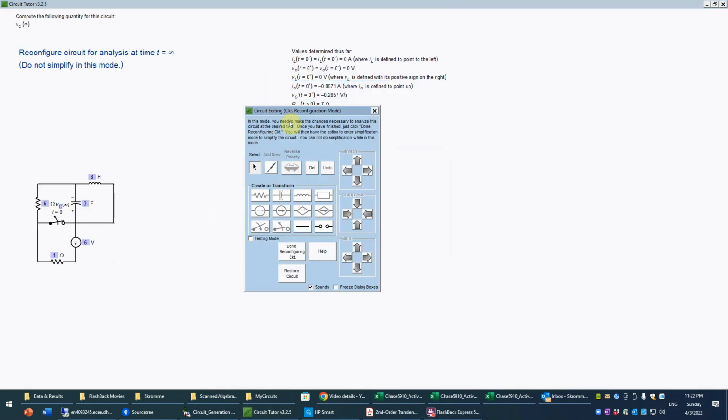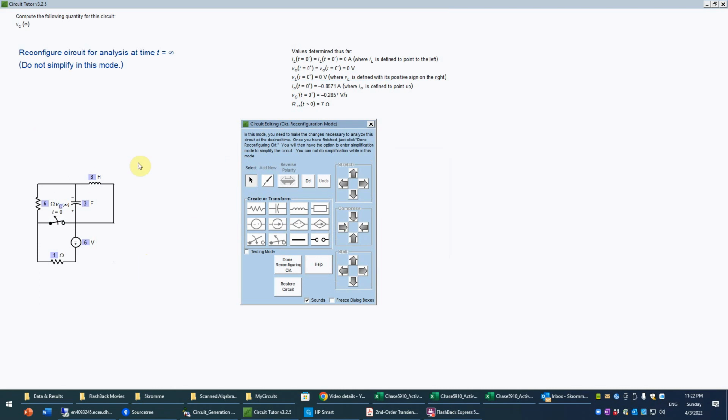And remember that at t equals infinity, because a long time has gone past and we're assuming this circuit is stable, which it is because our Thevenin is positive. And for that matter, we didn't have any dependent sources, so it has to be stable. So basically, we're going to be in steady state. Now, we'll first take care of the switch. And remember that infinity is, of course, greater than 0, so that switch is going to be open. So we delete it, as we did before.